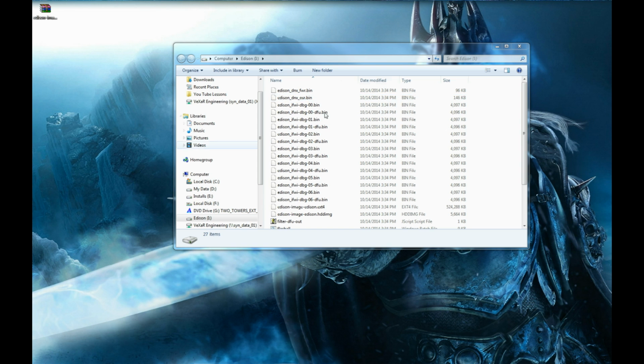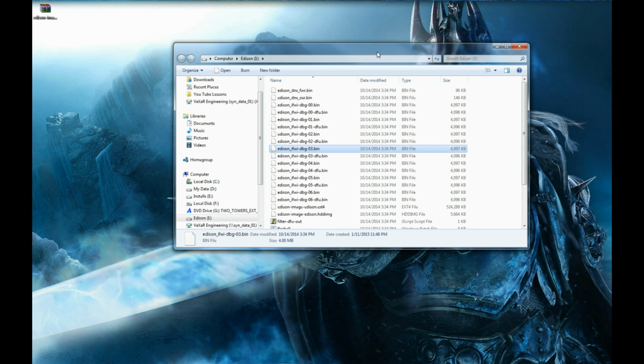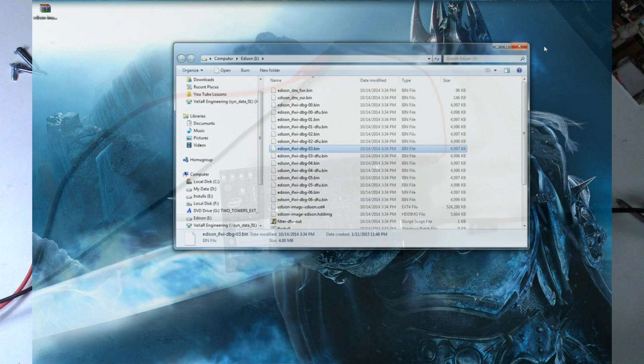Okay, so now it has finished. So basically it has decompressed that zip inside of that flash memory. So now all we need to do is swap the USB connector again, because we're going to pull up terminal software to then get into it and reboot it to where it will load the new image. So let's go back to the bench, and we will swap that cable.